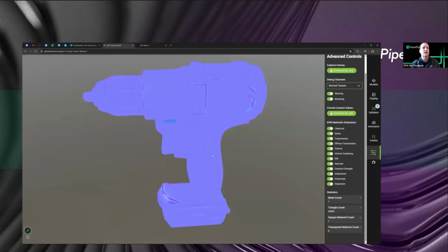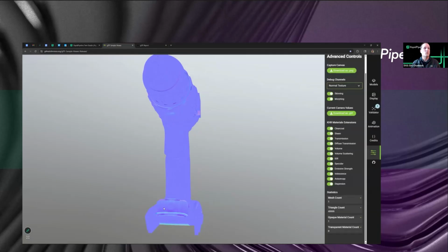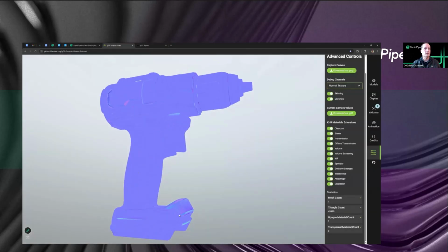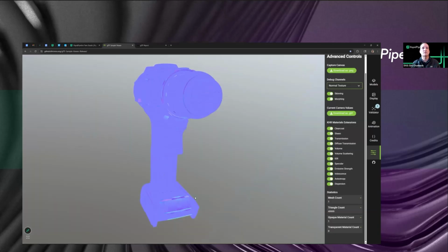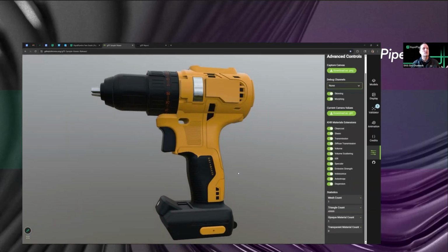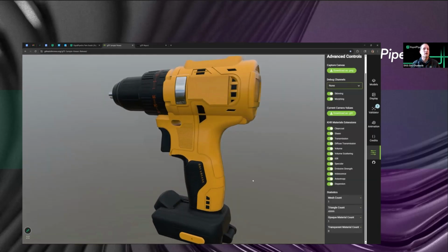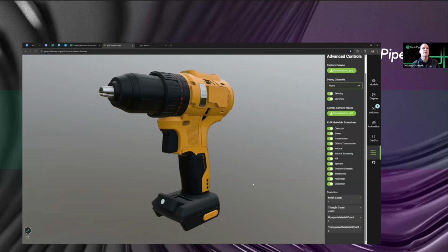The normal texture is there. And this has actually added some shading detail where it lost some resolution by going down to 50K triangles from 220 or so. So that's helpful in terms of if you want. You can also just disable that and say, hey, I don't want a normal map. You can remove that as well and just say, I don't want to bake that.